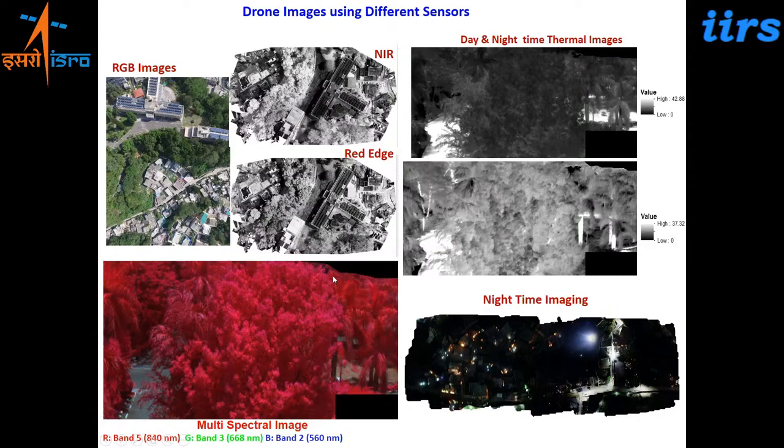Now, this is the flight planning which we mentioned. You need to plan how the drone will take off from here, start collecting data till here, and then after this point, it will come back and land at this point again. So this is how this entire image was acquired with this small flight plan. Right? So this is the near infrared and the red edge band which was then taken, and the NDVI of the same area was generated.